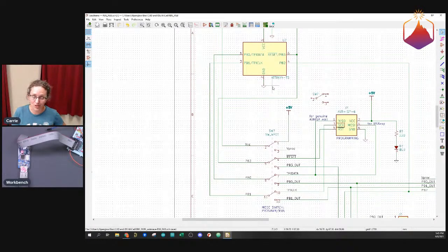So you have to switch the voltage to the processor if you're going to run it off of a supply that's not 5 volts. That's the other reason for having that switch there and having them all together, so that you don't accidentally hook up your battery to 5 volts when you're trying to program it. So that's what this switch bank is doing. It's just switching so that the lines are connected either to the programmer or to the rest of the circuit.